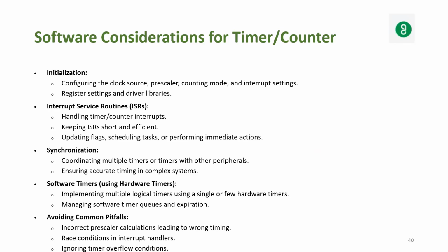Interrupt service routine: handling timer/counter interrupts. Keep ISRs short and efficient. That is, interrupts are kept short to make them efficient. Update the flags immediately after every task, and schedule tasks or perform immediate actions.